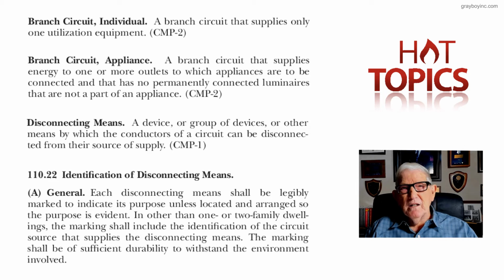Now, the other thing that becomes an issue, they talk about a controller and an enclosure at the air conditioner unit where you terminate this branch circuit that we disconnect in 110.22(A) when we use a disconnect. Is that considered an outlet, or is that just a termination point? Again, it's an interpretation of what one considers is an outlet.